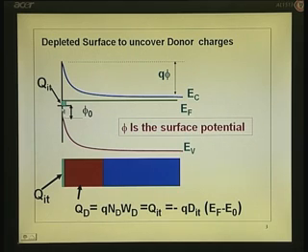So, band gap E_g minus phi_0 minus this total quantity is actually equal to q phi plus E_c minus E_F. So, all that you have to do is, on the left hand side E_F minus E_0, you can write from this total width you subtract whatever is above, which is q phi plus E_c minus E_F, and also this phi_0.